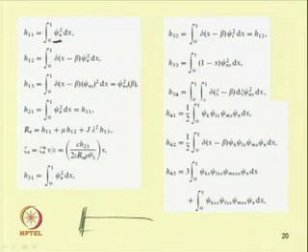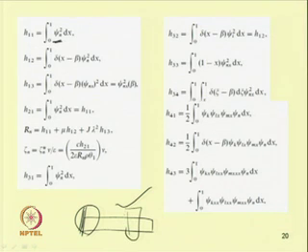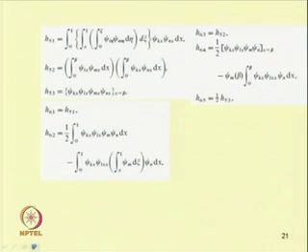One can also take the shape function of a cantilever beam, which satisfies the geometric boundary conditions at the left end, that is, displacement and slope equal to 0, or one can take the shape function of a cantilever beam with arbitrary mass position. By taking these, one can find all these integrals.